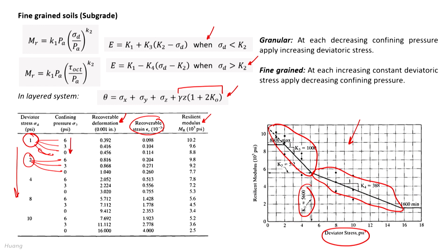and this is how we do the test. But you see this test method, the repeated triaxial test, involves on one hand a costly equipment, and on the other hand a lot of quality control has to be monitored during the testing process in the laboratory. So, instead of using the complicated process of testing these materials in the laboratory, researchers have tried to develop a correlation of resilient modulus with some of the parameters that can be easily determined in the lab.